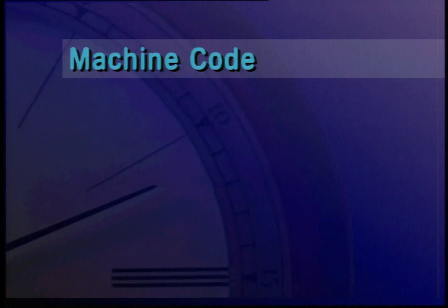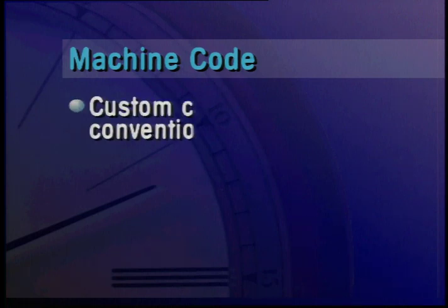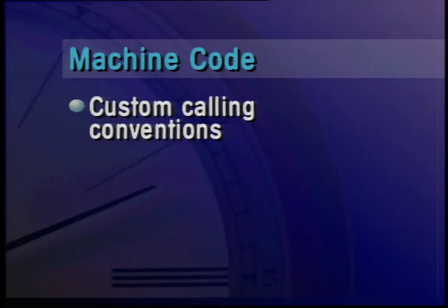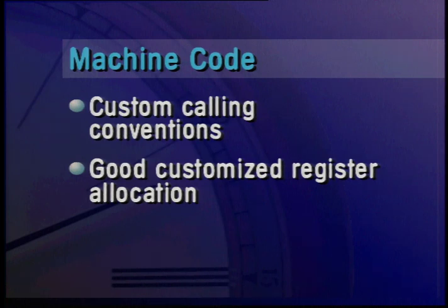On the other hand, there are some advantages to omitting native code. For instance, if you omit native code, you are free to use calling conventions which are not the standard C conventions. This may allow a lighter weight event routine calling convention, which can save quite a bit of time. If you can save a few instructions on every event routine call, that can definitely be a measurable amount of time saved. This may very well make up for the poorer instruction scheduling which the HDL compiler might do compared to the C compiler. Another significant factor is that the HDL compiler knows about relationships between variables that the C compiler must infer from the C source. This knowledge can result in better register allocation or code optimization, which can be significant.